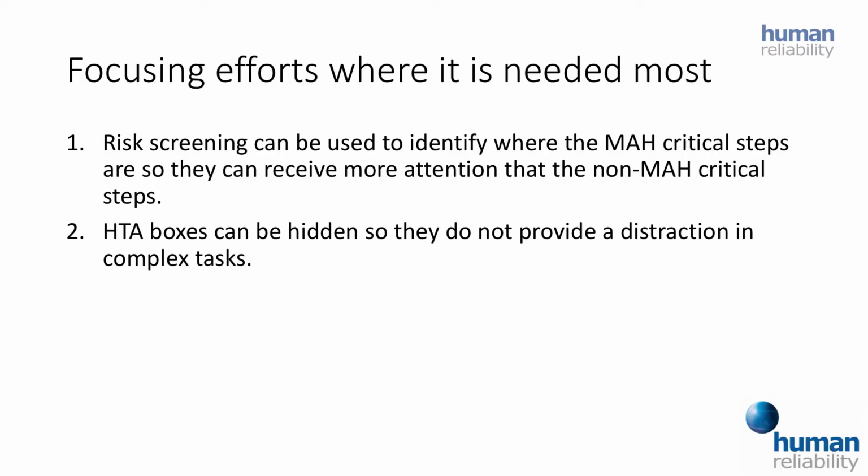There are some tasks that you might engage with that have major accident critical task steps throughout the whole task. And so from that perspective, it might make sense just to work through from step 1, step 2, and work through the task in chronological order, doing your failure and PIF analysis as you go along. But there are other tasks that don't have that even spread of critical task steps throughout it.